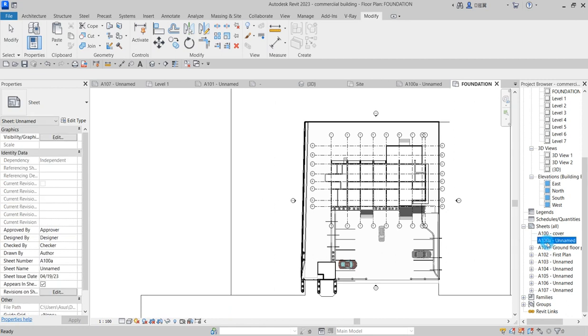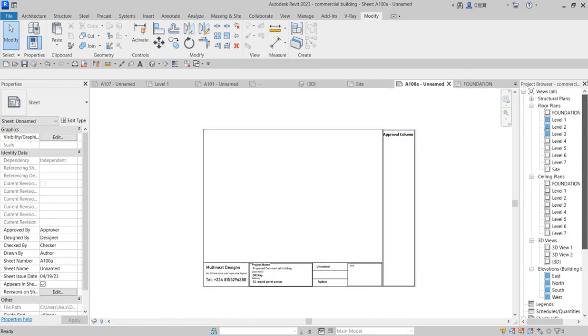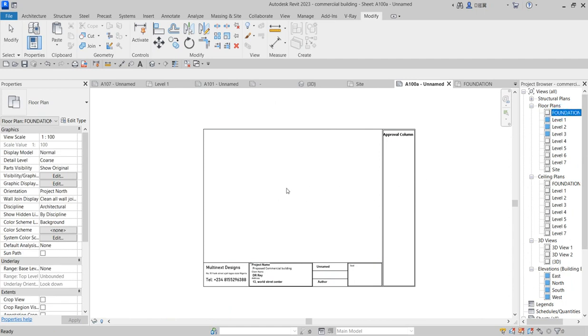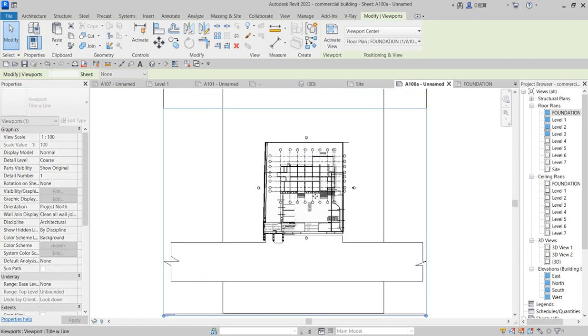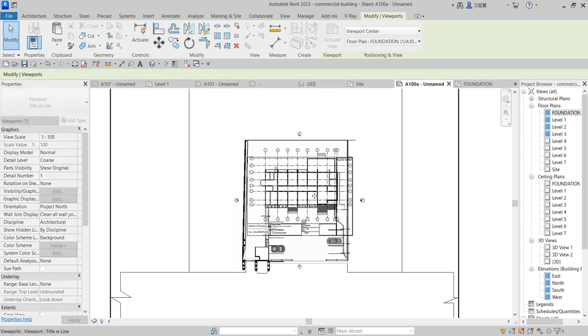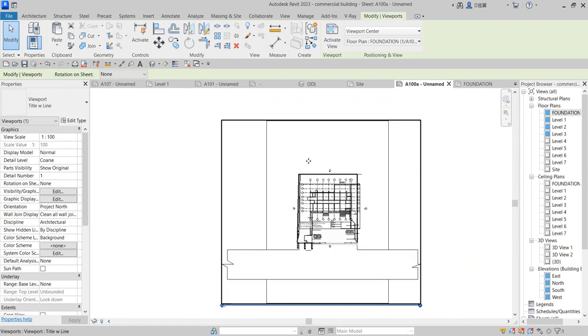So from here now, I want to use this particular sheet for the site plan. So we scroll up and take foundation and put it in the sheet. Let it be known to you, the reason is, if you have a cantilever house, it is not proper for you to bring the cantilever point as a site, because your site is always a ground plan scenario. So you don't put more excesses into it and confuse your drawing. So I always encourage people to use the foundation layout as the ground floor, as your site plan. That's what we do here.